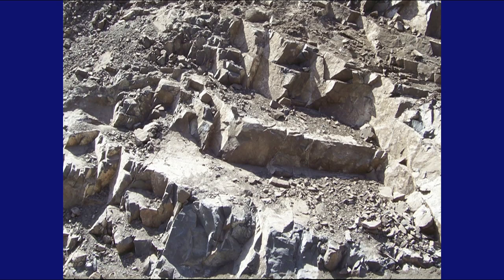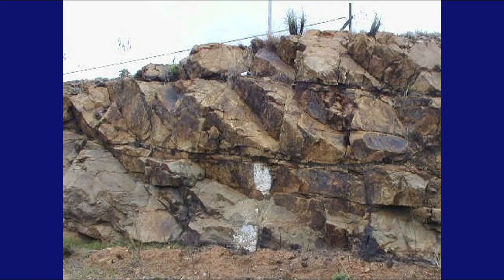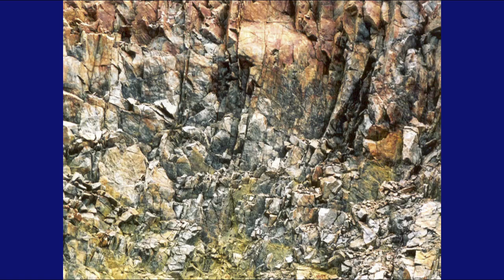This just shows another example of a rock mass in which rock mass classification is particularly applicable. It's an exposure in Chile, and it's close to El Teniente mine that uses block caving as a mining method, and rock mass classification is particularly applicable in that environment. This shows a small road cutting, and you can see a very different type of rock mass structure in that case. There are probably 4 or at least 3 plus random joint sets there. Here you see a very closely jointed rock mass, and it has also been blast damaged.